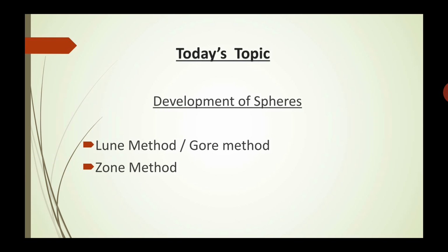We use the same principle in the lune method also, but the only difference is that the lune method is much more accurate for the development of the sphere.